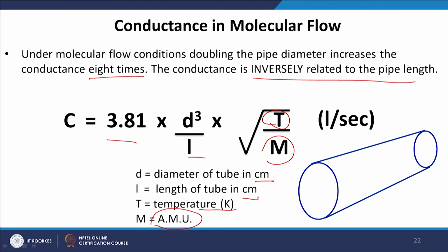So, basically what we have learned is that if we go from the atmospheric pressure to lower pressure, like if we use the roughing pump, the rotary vacuum, something like 10 to the power minus 2 millibar, or if we go to medium vacuum, high vacuum or ultra high vacuum, the number density of the gas molecules reduces drastically and the mean free path increases. We have derived an expression for the mean free path, and we have seen that mean free path is inversely proportional to the pressure, and as the mean free path changes, considering the characteristic dimension, we can define a quality factor which tells whether the flow is viscous or molecular or in a transition region, right.